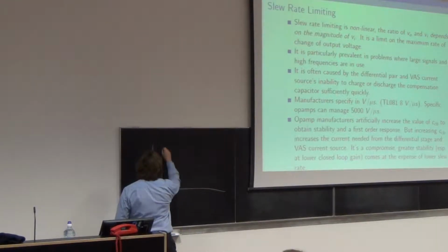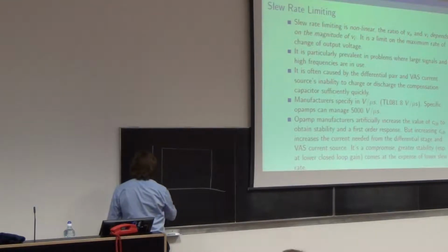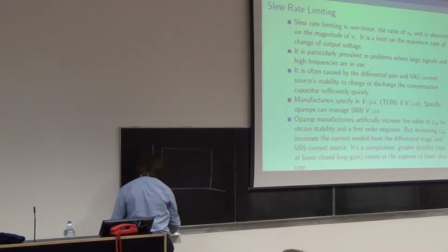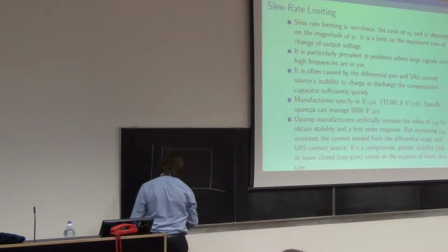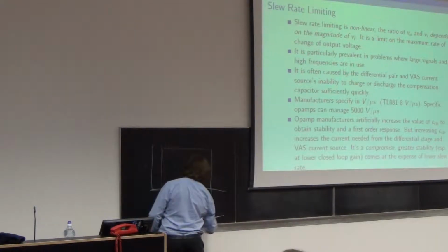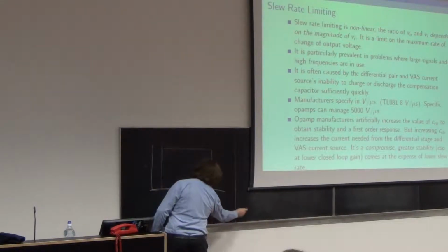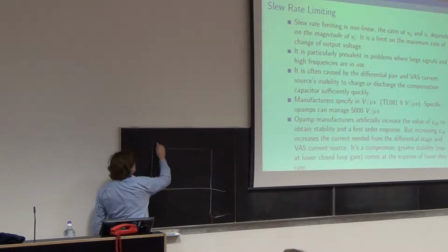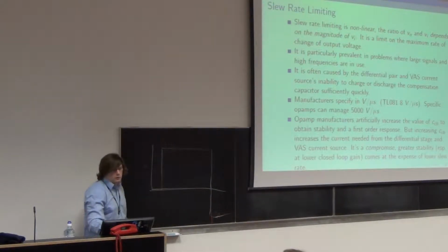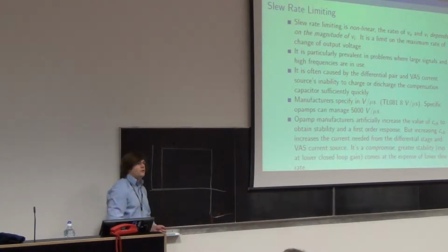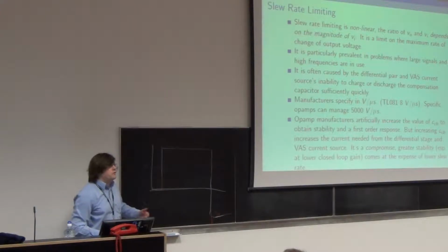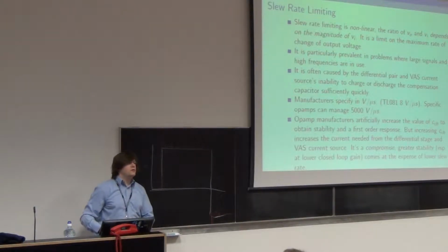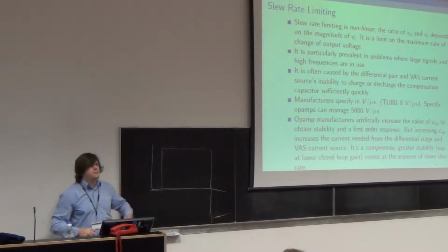Let's assume I put this in. So this will be V in and V out, possibly something like this. And if I have some other part to it, then similarly. So this underdampness up here is called ringing. We will see some more of that in a bit. And that should tell you immediately it is more than first order, because only second order and above can exhibit this resonance. There's another way of expressing resonance.